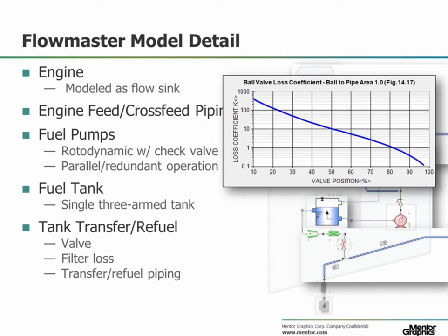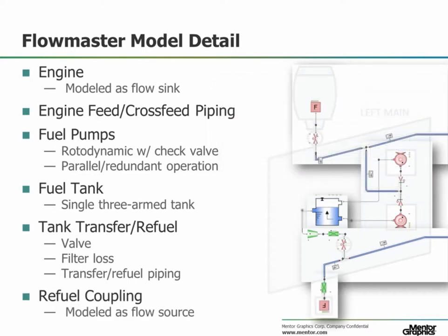You can also see piping to model the transfer and refuel gallery. And lastly, the refueling port modeled as a flow source component along with another discrete loss to model the pressure drop across the refuel coupling and a filter screen.